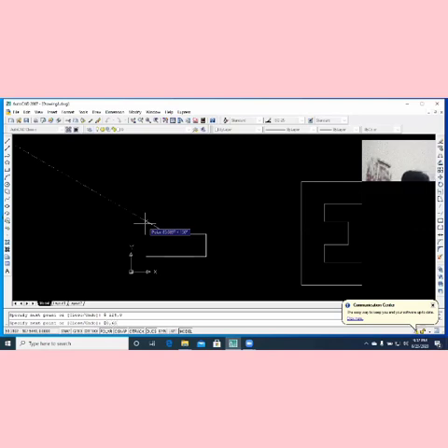You go to Shift Alt 0, 60, you enter. Shift Alt 80, 0, you enter. Shift Alt 0, 75, you enter. Then Shift Alt minus 80, 0, you enter.